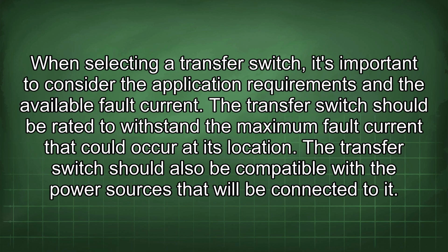When selecting a transfer switch, it's important to consider the application requirements and the available fault current. The transfer switch should be rated to withstand the maximum fault current that could occur at its location. The transfer switch should also be compatible with the power sources that will be connected to it.